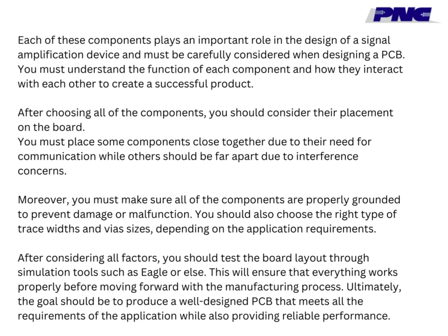After choosing all of the components, you should consider their placement on the board. You must place some components close together due to their need for communication, while others should be far apart due to interference concerns. Moreover, you must make sure all of the components are properly grounded to prevent damage or malfunction. You should also choose the right type of trace widths and via sizes, depending on the application requirements.